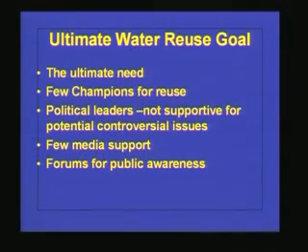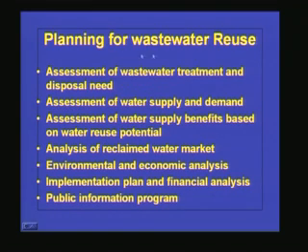So if you want to go for the ultimate water reuse, we have to plan in the following way. First we have to assess the wastewater treatment and disposal need, then an assessment of water supply and demand is required, and assessment of water supply benefits based on water reuse potential is essential. Then the analysis of the reclaimed water market, environmental and economic analysis, implementation plan and financial analysis, and a public information program. All these things are essential before going for any wastewater reuse program.